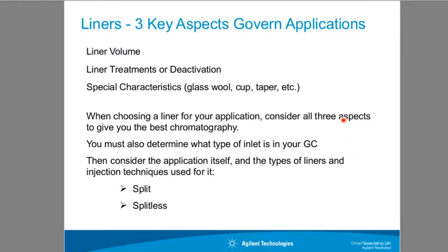So you want to consider all the aspects of the liner to make sure you're going to get the best chromatography, because they all play an important role in getting your sample onto the head of the column, and that's one of the key things with the inlet itself. With that, as I mentioned starting off, if we're using a splitless inlet, there are liners specific for split injections, and there are liners more specific for splitless injections. So we want to choose a liner that's appropriate for that in developing a method.